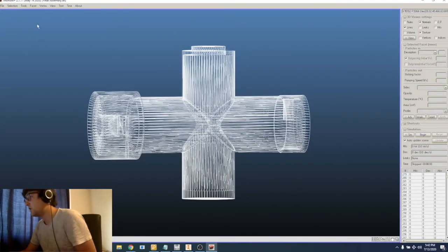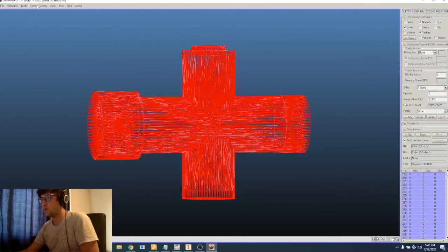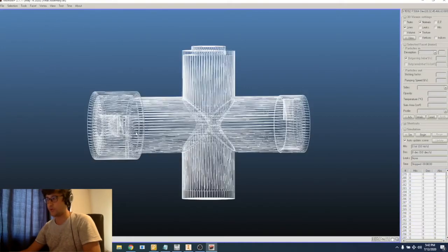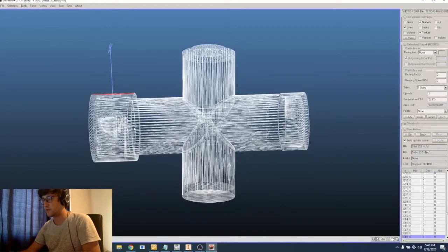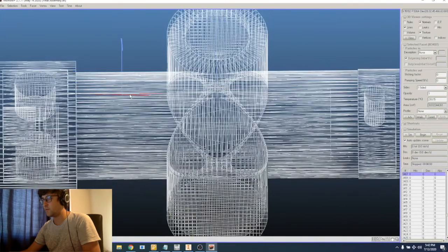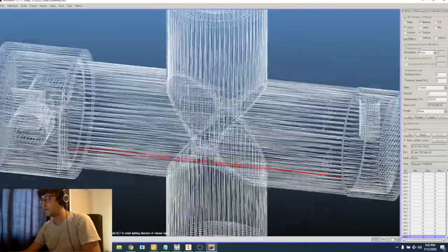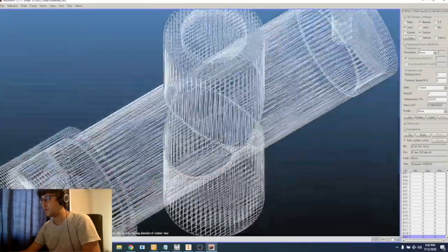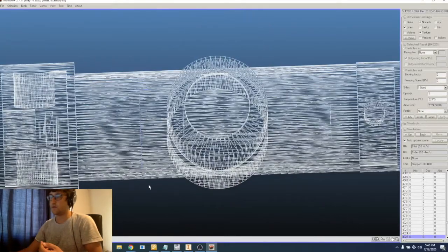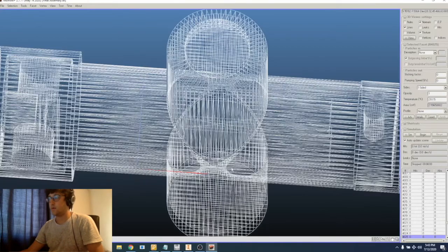Okay, so after that, I select everything, and then I go up and swap the normals, because for whatever reason, all the normals are inverted from what I actually want. Now when I click on something on the outside of the vacuum chamber, it's pointing out, and if I click inside, you have to double click sometimes to get the interior. So there's a facet on the inside of the wall, and you can see it's pointing towards the interior.